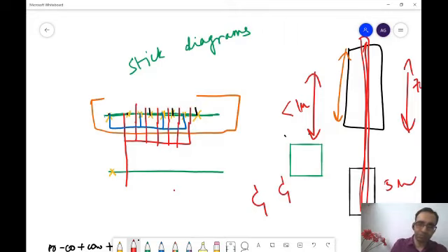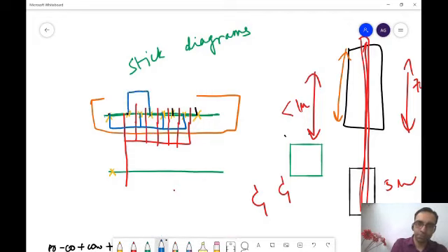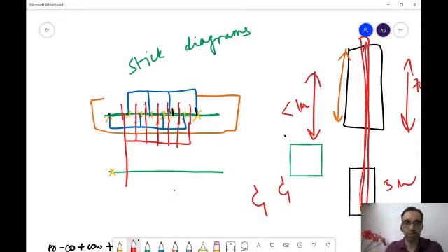Why not connect all the 8 contacts with a single metal running? You're missing 2 sets, right? Okay, you tell me, you should have the answer for this. We are connecting the drains together and the sources together, right, sir? Yeah, if I connect all 8 of them together, then all the sources and drains will be shorted. Yes. Okay.